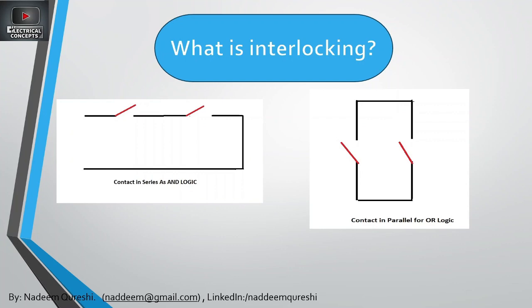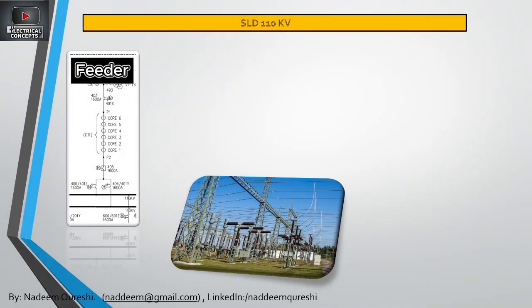You can remember it in a substation specifically: an interlock ensures that certain electrical devices such as circuit breakers, switches or transformers can only be operated in a safe and coordinated manner. Interlocks can be of mechanical type, electrical type and software interlocks. In modern substations we have wired interlocks, called hardware interlocks, and software interlocks through the SAS system. Both are done in a redundant way, so we have a double confirmation before the operations. Now let us move to our next slide, which will further show how these interlocks are implemented.